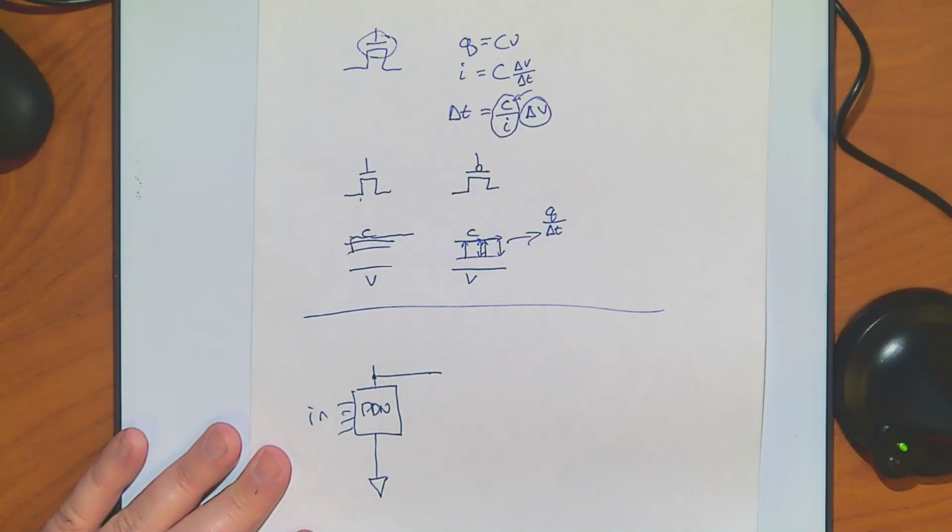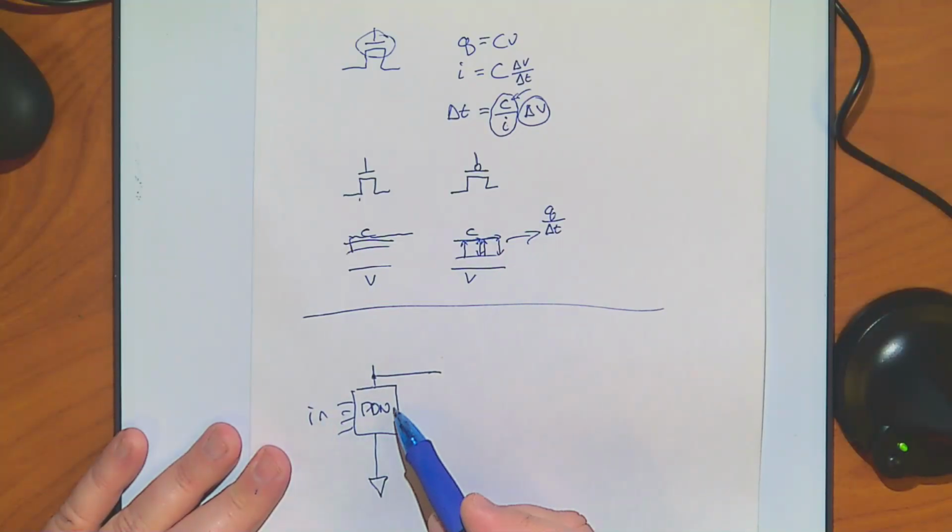Remember we said you can build these with Karnaugh maps? If you do Karnaugh maps and you do encirclements of zeros, that's where they come from, right here. So whenever this pull-down network, a gate opens up, any of the things inside the encirclements, it'll ground things for you.